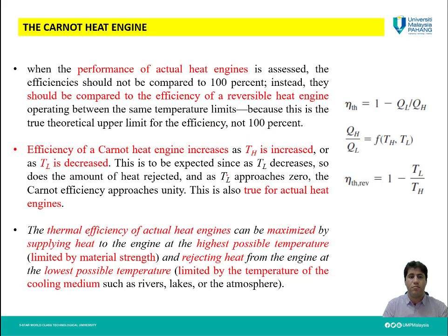And so however, the efficiency of an actual heat engine may just be 20 or less than 40%. But if we compare that with the Carnot cycle, we may find out the thermal efficiency of our engine, which we have in actual, is 70% of the thermal efficiency which we have for the Carnot heat engine. So we can see how we can use this Carnot heat engine to check the performance or efficiency of our heat engine.